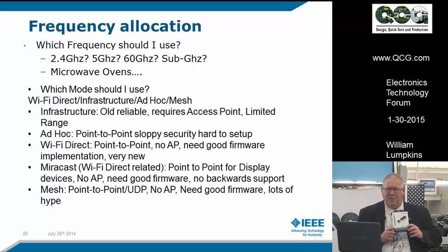It's a great thing. Actiontec ScreenBeam TX, a great little product. It should work wonders. We tested this. You plug it in, and you should be able to beam all the content from your laptop straight to your television set. Unfortunately, it doesn't work very well. The Wi-Fi is fine, but they didn't consider power considerations on HDMI. They plug into the HDMI in the TV, so they didn't worry about the HDMI power considerations. Anytime there's a power fluctuation on the HDMI plug itself, it causes the chip to reboot and you lose connection. We tried for about 8 hours straight to connect in different office space locations, and it was almost nearly impossible. We could see the signals with a Wi-Fi sniffer.